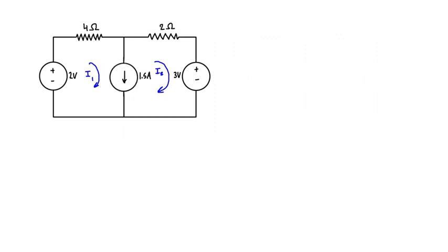If you do want, you can label on the assumed direction of these currents. Let's say it's like that, and let's just assume this direction for IB. We don't really know, but we can just pick a direction. When you do that, it's basically going to assume the polarities, which we're going to need later when we actually apply KVL. But we'll get to that in a second.